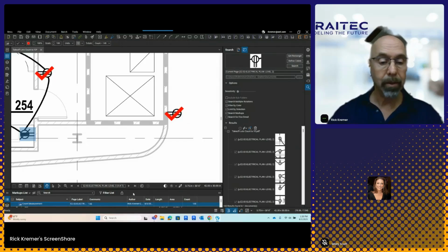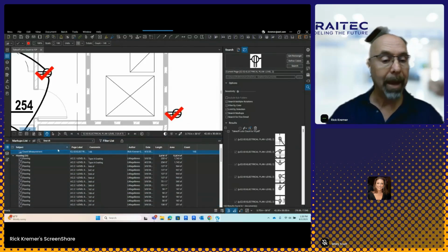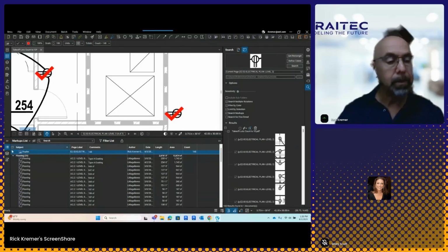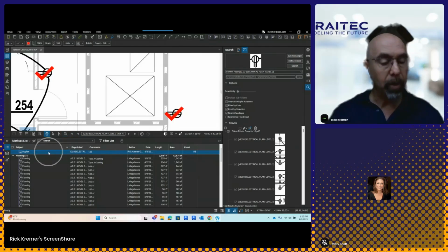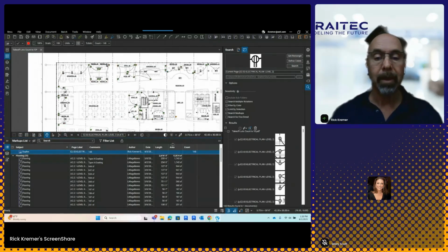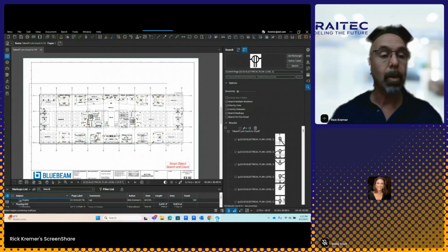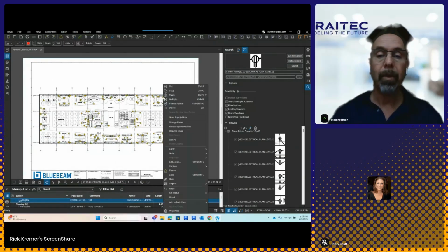When I select it over here, it's going to tell me how many I have, but remember, it's generic. It says 148. So what do I do? I simply double click in there and call this a duplex. Now I know that this is going to be labeled correctly as 148 duplexes. And if we go all the way out, I can see them. And just like before, I can window around all of them, right click, and create another legend.